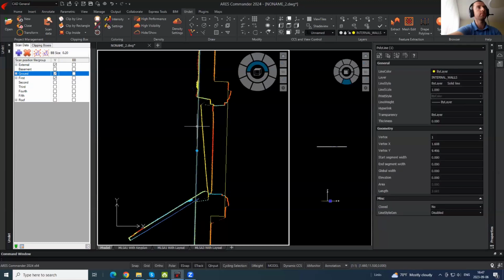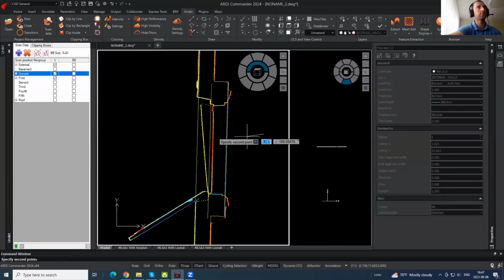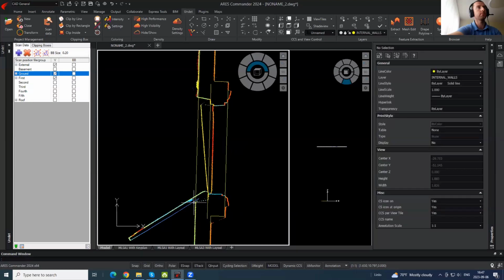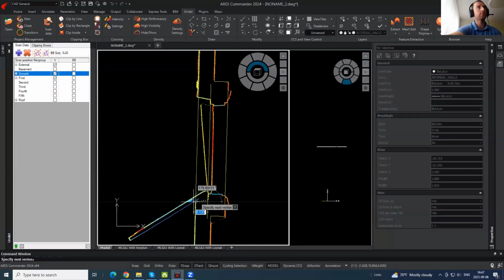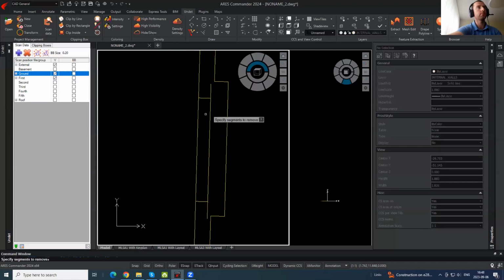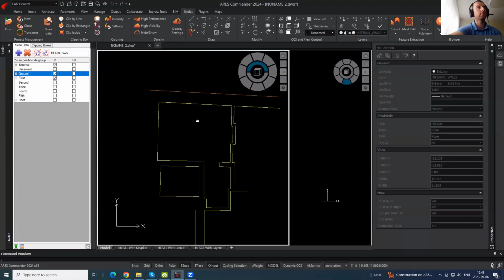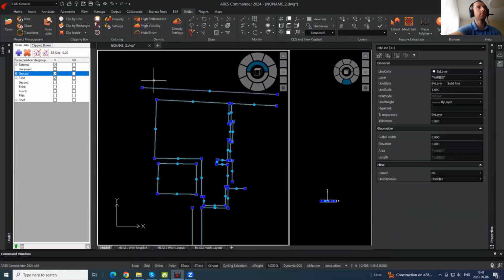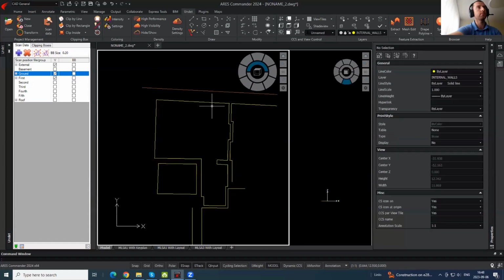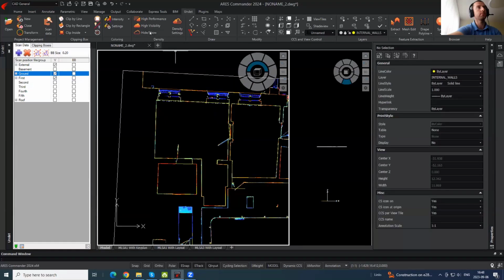We have some strange situation, but let's do it like this, I guess it's a door and a wall. So now we will have walls by cut line, vectorized. As you can see, there are polylines. As you see, we use the point cloud as a background for drawing. And now the first step is done.